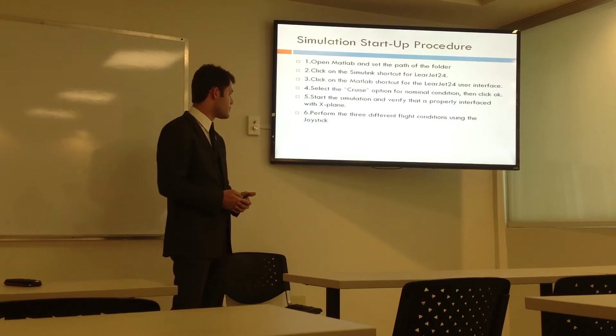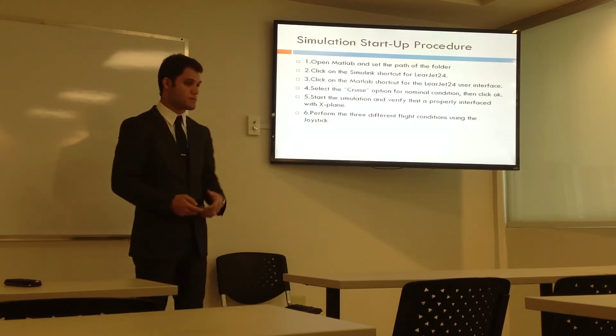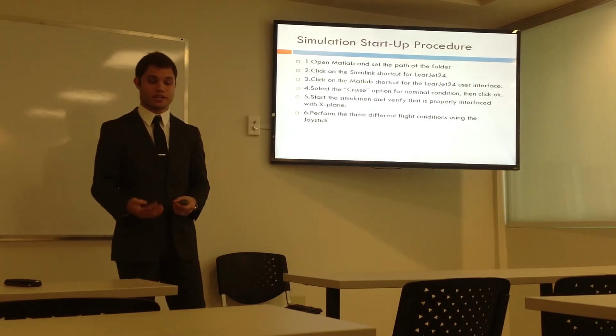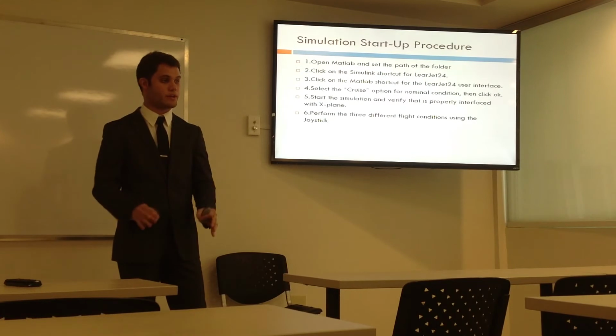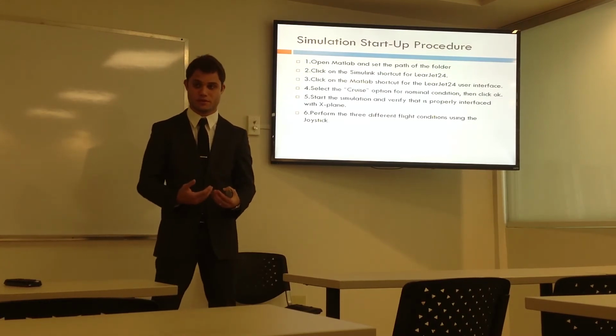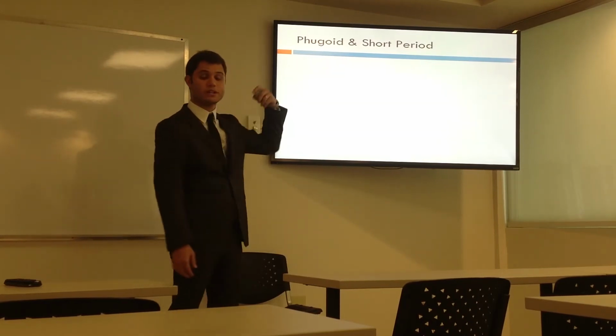And then you're just going to perform the different flight conditions using a joystick. There are 4 different flight maneuvers that you do in aircraft testing. They're universal for every aircraft. They're there to determine the stability of the aircraft and its handling qualities. So I'm going to discuss those now. First we have what's called the phugoid and the short period.